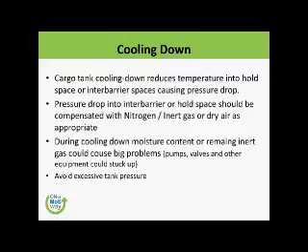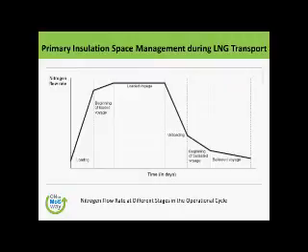Avoid excessive tank pressure. Do not let the tank build up pressure. Okay, so insulation space management during LNG transport: this is the nitrogen flow rate in different stages. While you are loading, very high. Beginning of loading, slightly low.